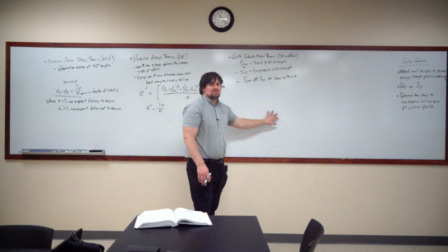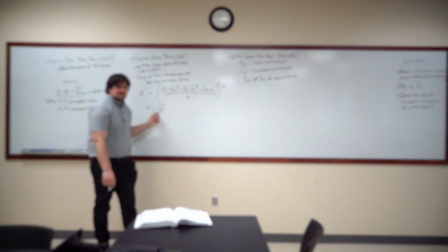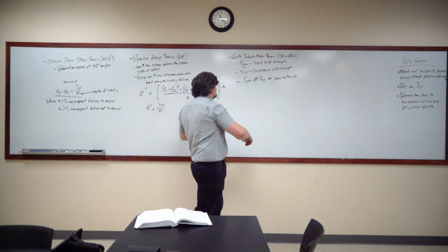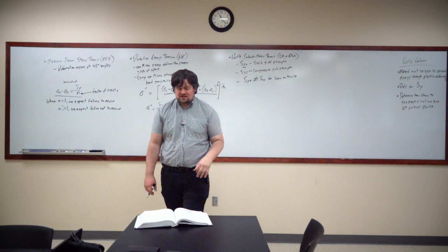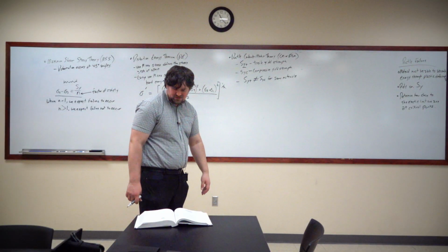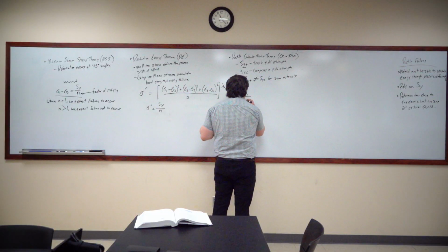If we don't have the same, unfortunately, we can't use these theories, because these theories would require us to have one consistent definition for a yield strength. When our one consistent definition for a yield strength isn't just tension or compression, then we have to have something different. Okay, and so in ductile Coulomb-Mohr, the equation becomes sigma 1 over SYT.